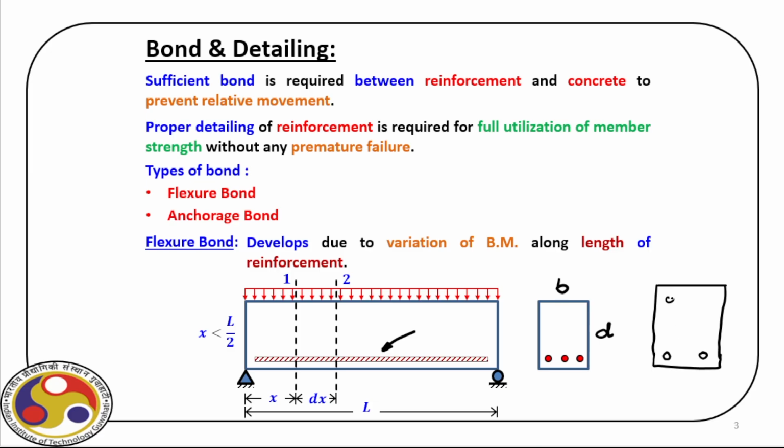We also have additional rebars we do not consider in a singly reinforced beam, but these rebars actually hold the stirrups against shear force. And then together they give a rectangular shape to this beam.